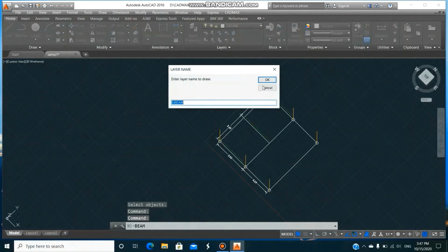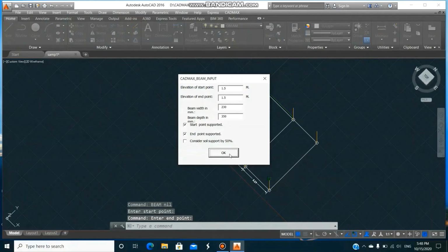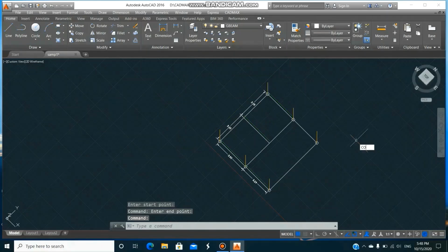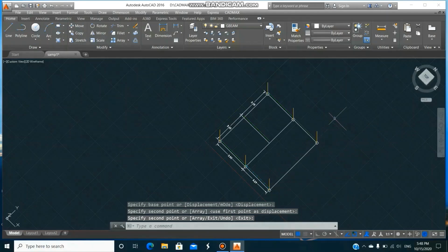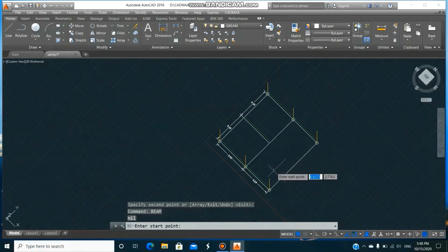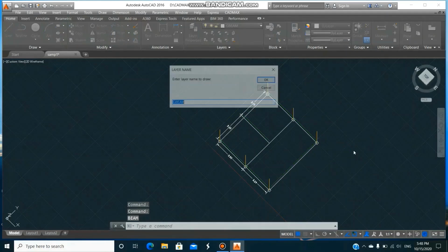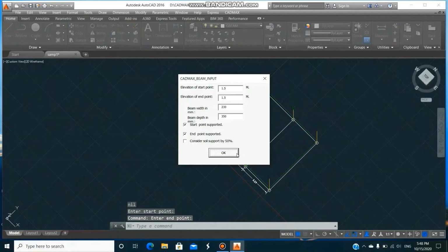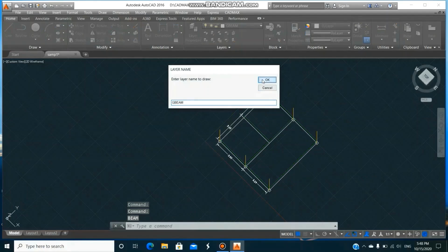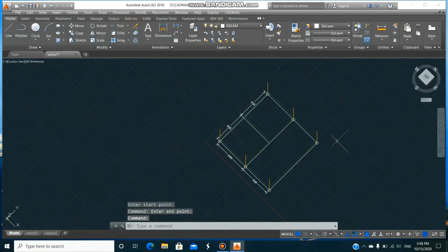Give one more beam. This point to same 230 by 350, and copy the same, this point to this point. Then beam command. Can click on the menu, give the same size. Press enter for previous command. So this is the grade beams drawn.